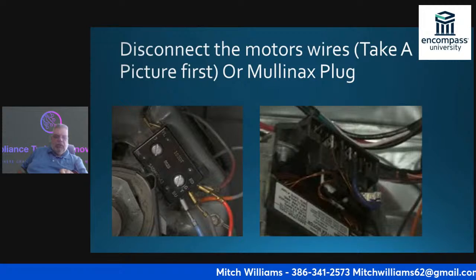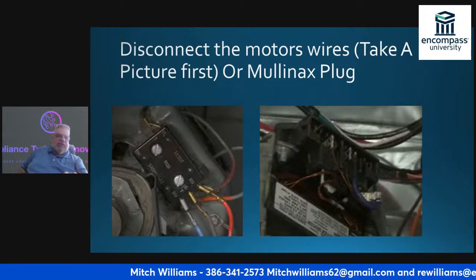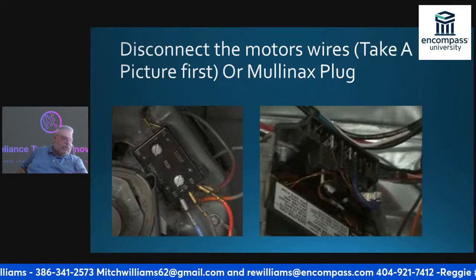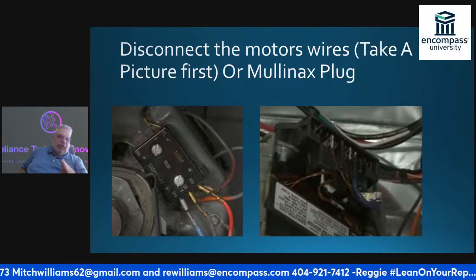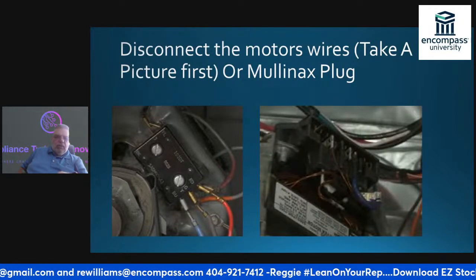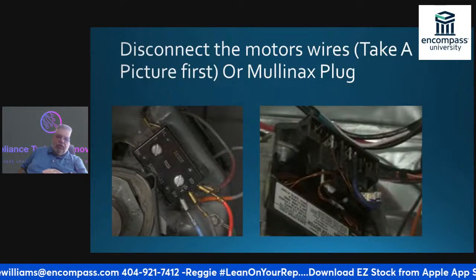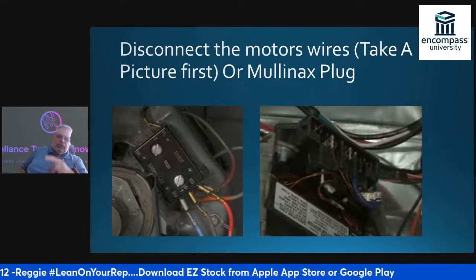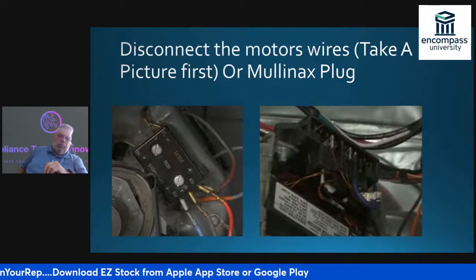On this particular motor, if something happens and it's in that switch, I actually can replace that switch. This is the old style motor. The one on the right is the new style motor. Once again, I'm going to ohm through the switch to make sure that the switch is working properly.